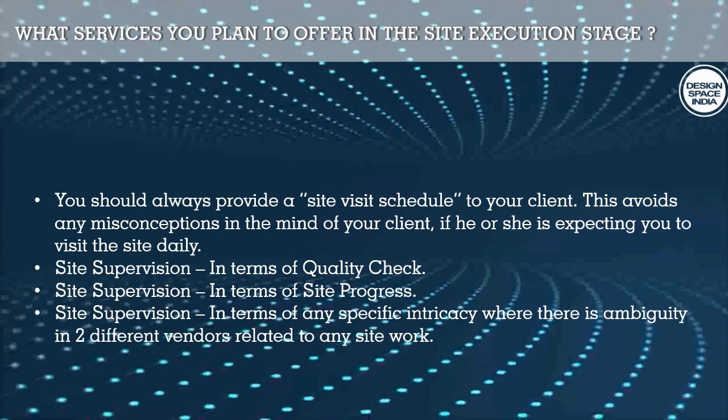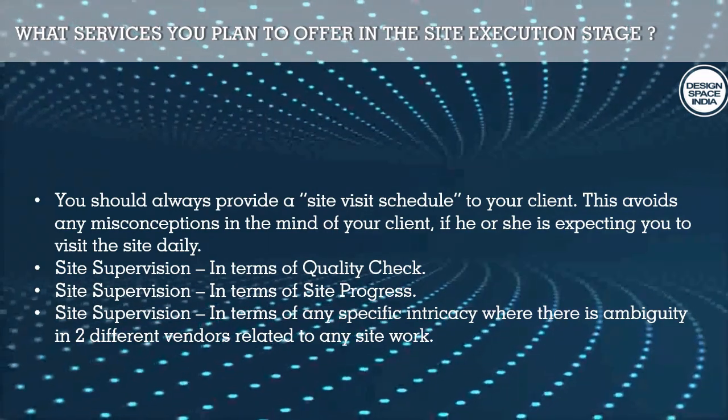What services you plan to offer in the site execution stage. You should always provide a site visit schedule to your client. This avoids any misconceptions in the mind of your client if he or she is expecting you to visit the site daily. Site supervision in terms of quality check. Site supervision in terms of site progress. Site supervision in terms of any specific intricacy where there is ambiguity between two different vendors related to any site work.